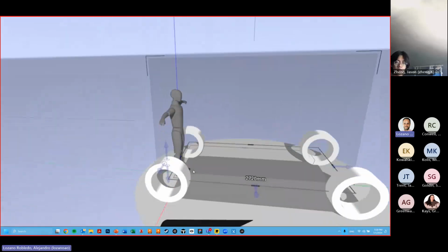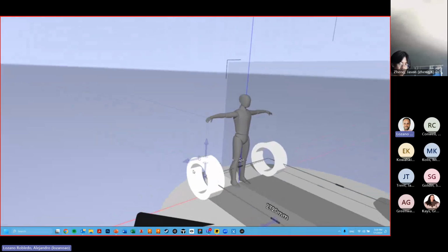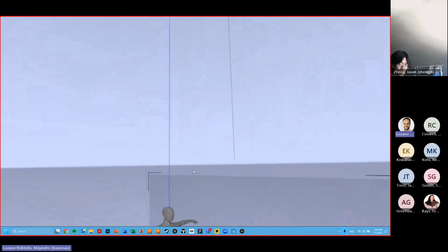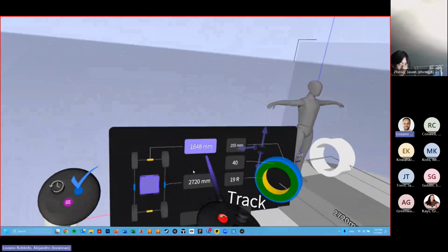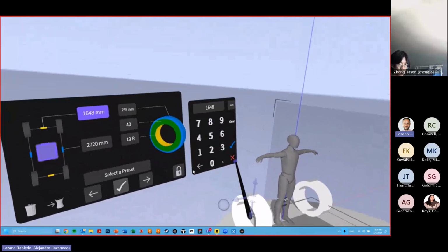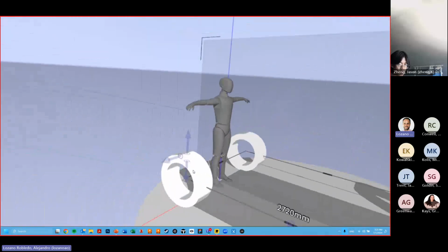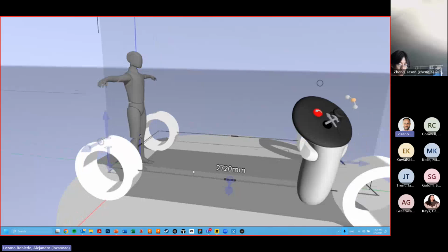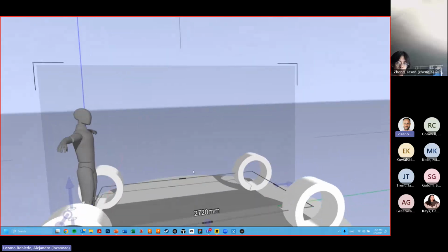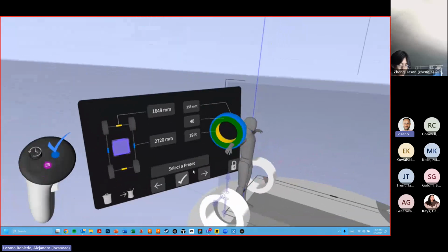This is a built-in tool that Gravity Sketch developed for mobility design. It's extremely helpful. Many of you from my conversation at the beginning, you know already exactly what the dimensions are. So please input them. You can click here, type in the number, input that. If you have more of a freeform package right now, look at how many different arrows I have. So let's do an example. Some people in the class mentioned that they're building a micro car.